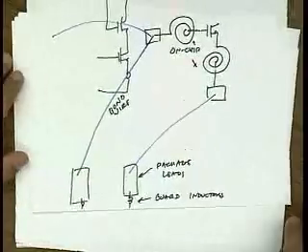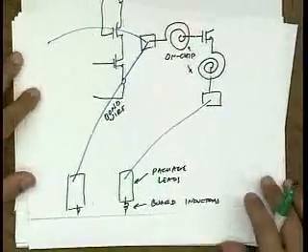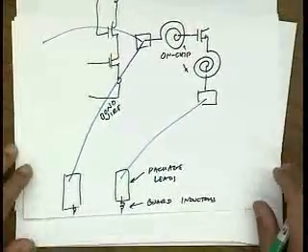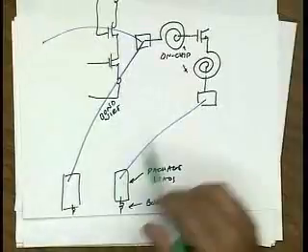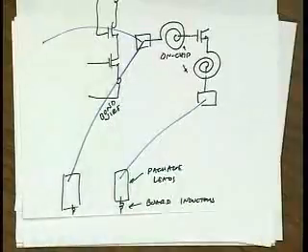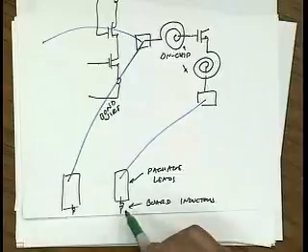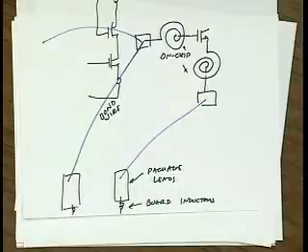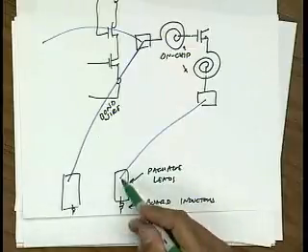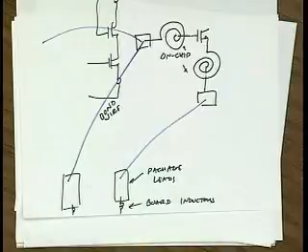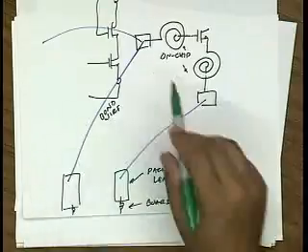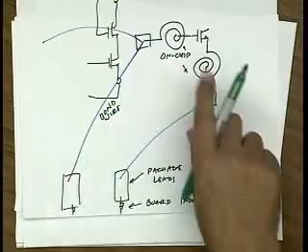Okay. Now from a design manufacturing perspective, this may seem a little bit like a nightmare, right? Because these bond wires can vary, their lengths can vary. Traces on the board, the amount of inductance you pick up can vary depending on the board height, the distance to the ground plane. Essentially on the board, the traces look like transmission lines if you do it right. And so this topology requires a lot of fine-tuning in order to get the matching right.